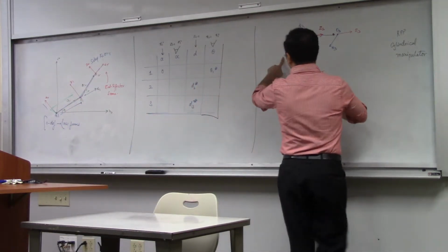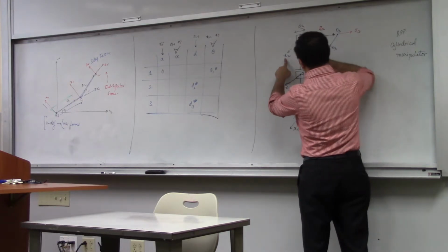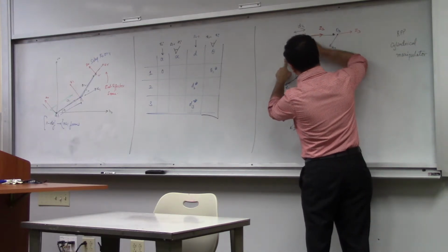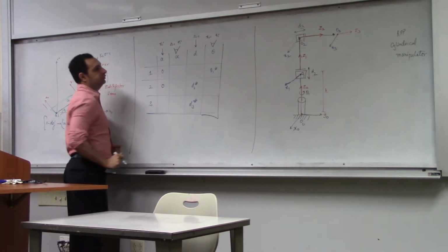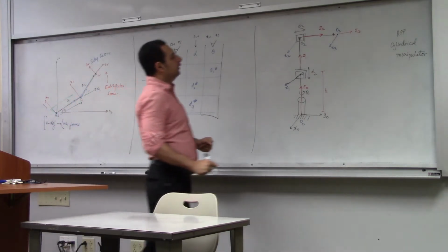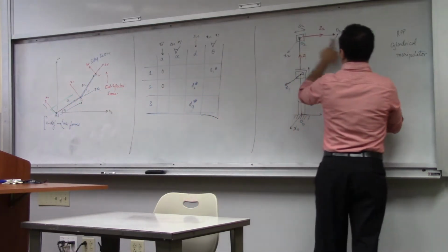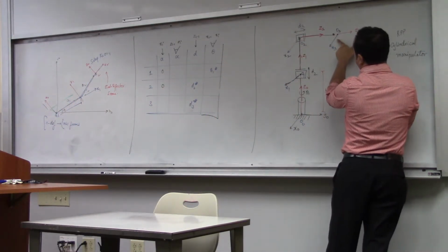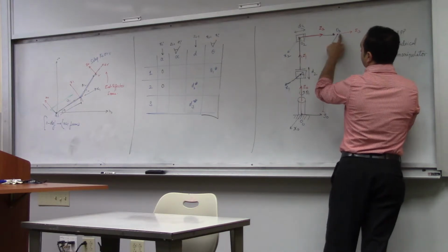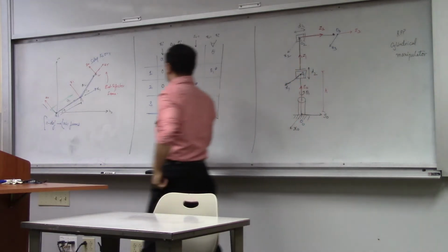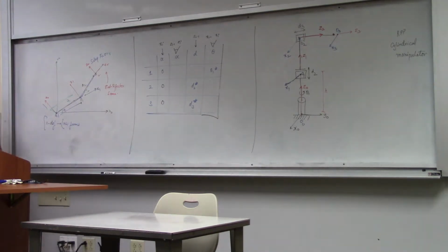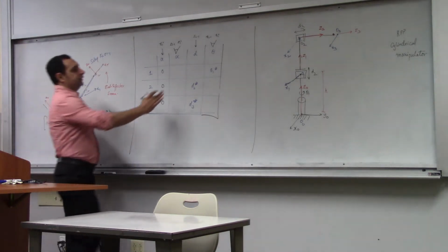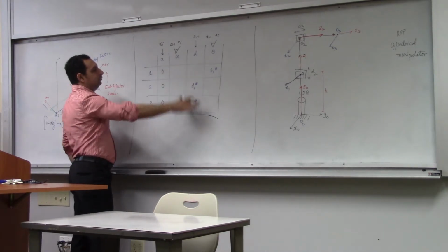Let's do the same thing here. A2 is distance along x2 till it is intersected by z1. Again, z1 is intersecting here, so A2 will also be 0. Same thing here, because if you want to measure distance along x3, z3 is intersecting exactly at the origin. So this is also going to be equal to 0. All right, let's do D first, and then we'll come to the angles.